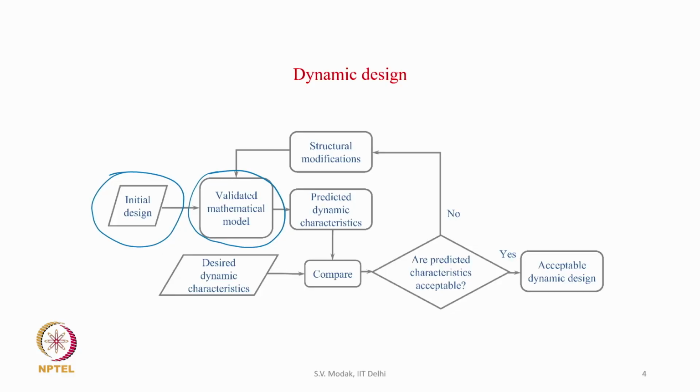This model can be based on finite elements, it could be a finite element model or a numerical model. Other possibility is to use a model identified through modal test, and that would require a prototype based on the initial design to be built and then modal tests carried out on that prototype. In the context of discussion in this lecture, we are assuming that this model has been identified through modal test on a prototype of the product based on the initial design, and that experimental model is then further used.